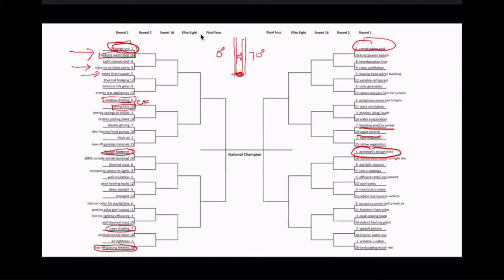Now, over time, sometimes there'll be leaks and air will come in anyway, and then even in an argon-filled window, it might not have argon in it anymore, and there may be condensation in between the two panes of glass in the IGU, the insulated glazing unit. But generally that's the idea. Less moisture and less heat transfer by a little bit. Well, less moisture by a lot, less heat transfer by a medium amount. Not insane, but well worth it.